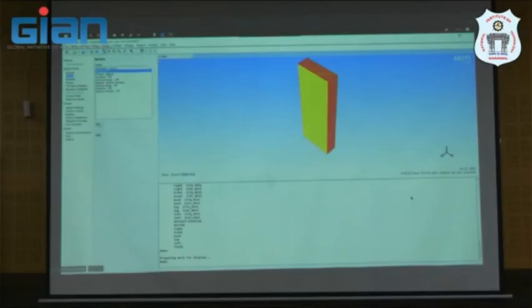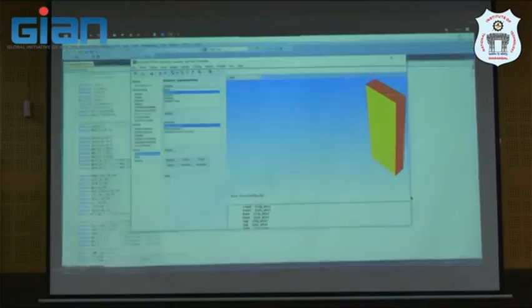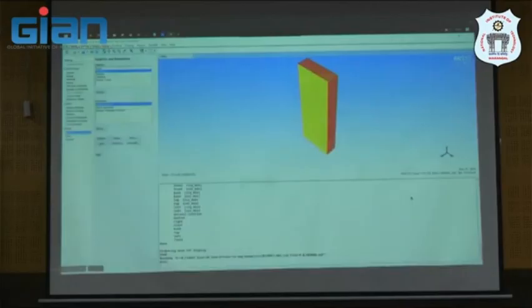And we will open the energy equation, and here is the material, and the properties of the material are written by the UDF. And the thermophysical property for each phase, that you define for the system. So we have about 7 phases, I see previously. So you have aluminum liquid, solid, and then copper liquid, solid, and then what? Yeah, that's right.